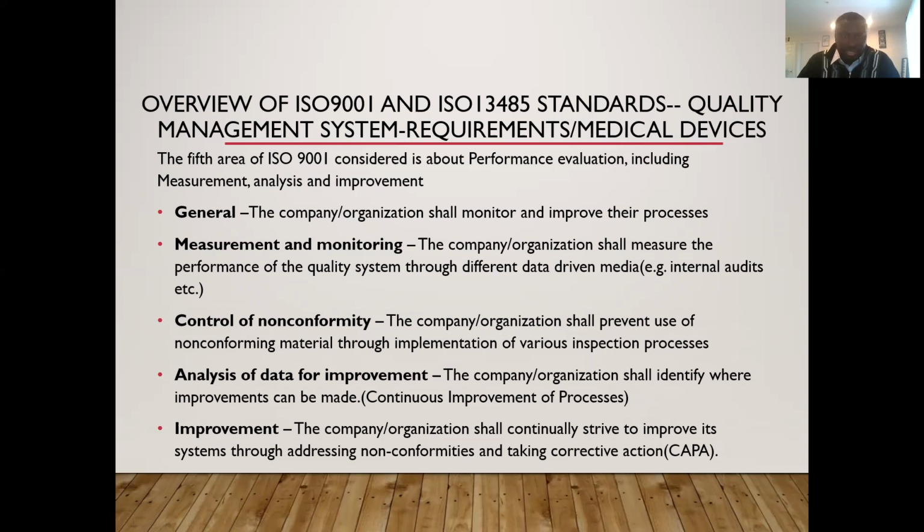Measurement, analysis, improvement, if I could talk a little bit about it, it also touches on suppliers. It touches on, I'll say, purchasing controls too. There are so many things that go in place: how you are monitoring your suppliers, and measurement analysis. How are you also measuring the improvement of your suppliers, the non-conformities that come from the supplier standpoint, from incoming inspection, from in process, and also from final inspection. All these things are the requirements from the ISO 13485 and ISO 9000 standpoint for the medical device industry.